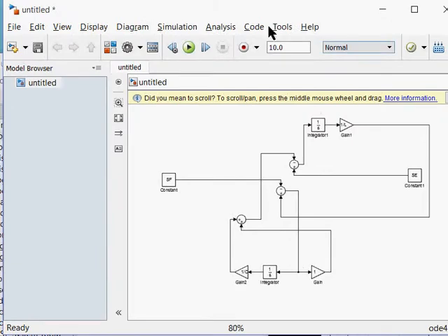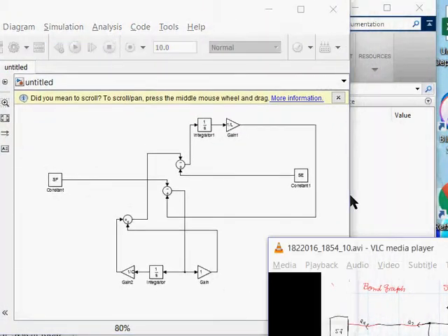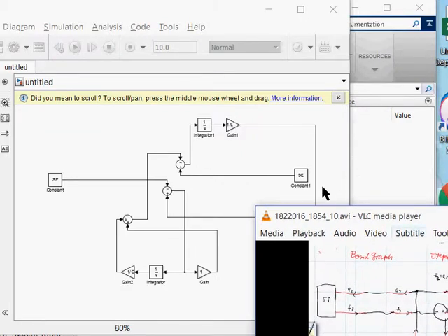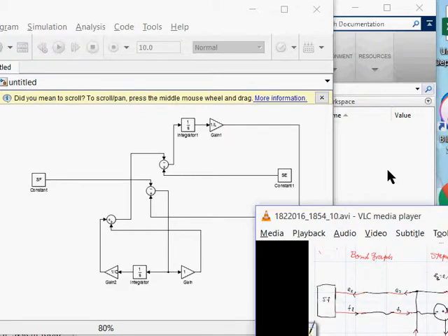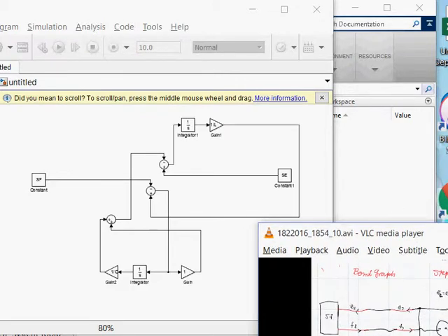this one produces just the flow. And in here I think it's a good idea to complete this element. There we go. And this way we have completed translating my block diagram that I produced from the bond graph model into Simulink. And from here we could do a simulation and pick up any values, perhaps any outputs that we want.